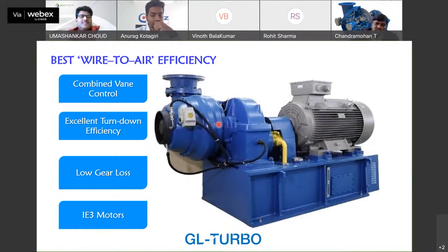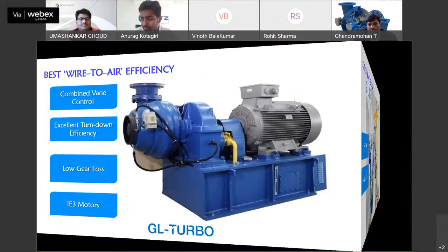But as far as the cement industry, let us focus more on the cement industry here. So here, in most of the applications, what we are seeing is kiln firing and conveying applications, majorly somewhere between 3,000 to maybe 7,000-8,000 meter cube per machine. In that way, this particular technology will work very well, and the efficiency is much, much higher compared to your existing PD blowers, if at all you have them.